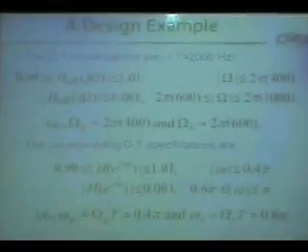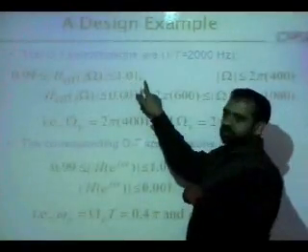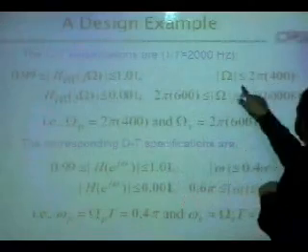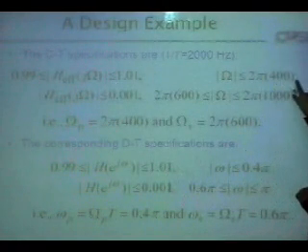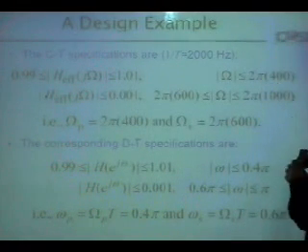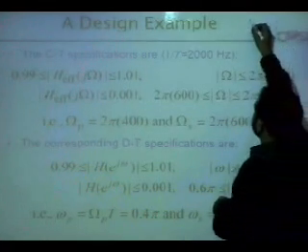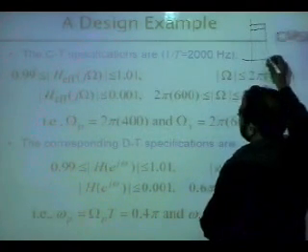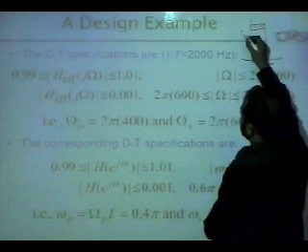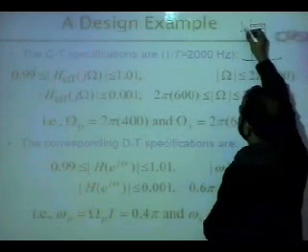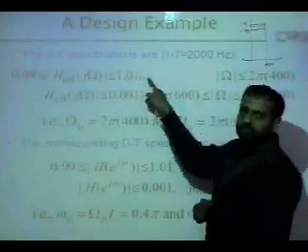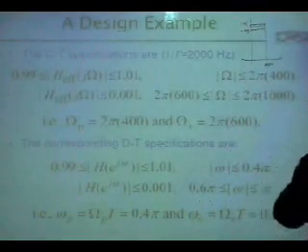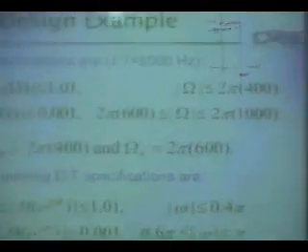So usually you will be asked to design a filter, and remember this 1.01, you want these frequencies, 400 hertz, 2 pi fa. Okay, 400 hertz. So if I draw this, you want up to 400 hertz. You want it to never go below 0.99 and above 1.01. This is how the specifications are written. So you don't want that.